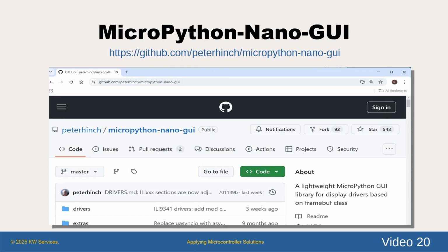This graphics library was developed by Peter Hinch. Peter's library has drivers for 30-plus LCD displays that support a common primitive graphics API, a writer class with fonts for text, and some widgets. The small displays use I2C or SPI with optional control I/O to communicate with hardware that utilize the MicroPython framebuffer module.